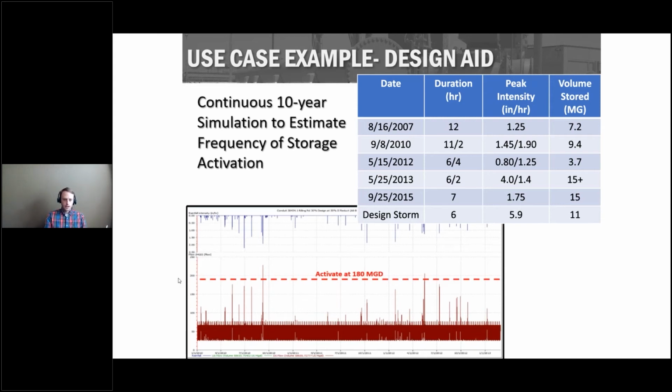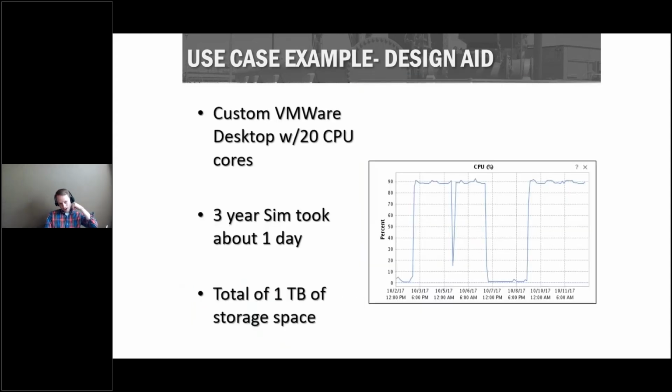And like I said, there's a lot of ways to do this. You don't necessarily need ICM to do this, but it can do it, and it creates some really useful graphics when it does. One thing to be aware of, if you do those long extended runs for multiple years, it can eat up a lot of processor power and take some time. And then the simulation files can be quite big, so just be aware when you set one of those up, if you're not going to do anything to prune down the rainfall data, it's going to generate some really large results.